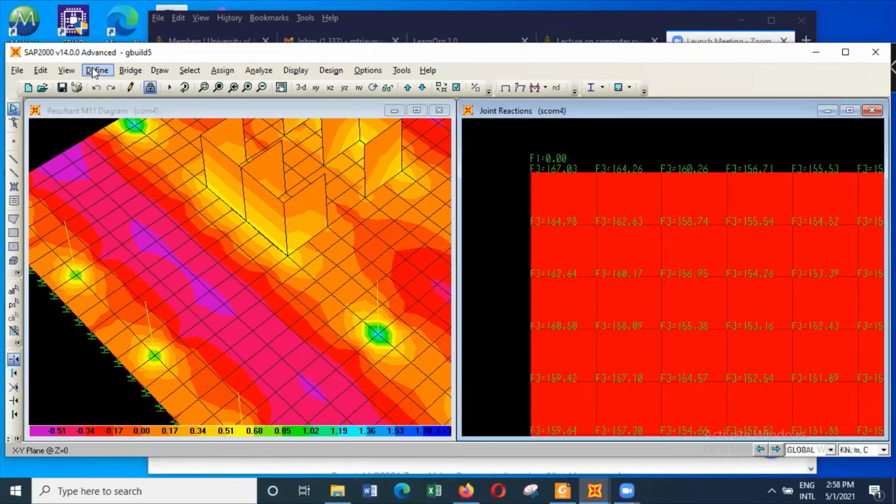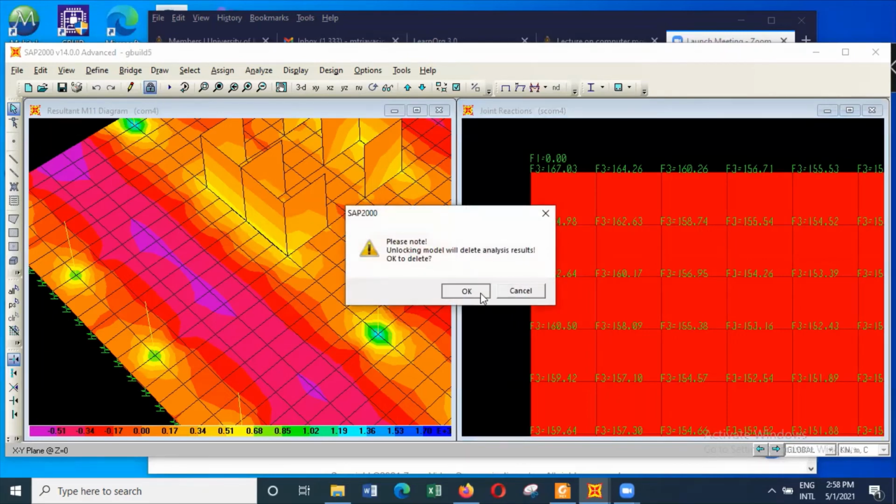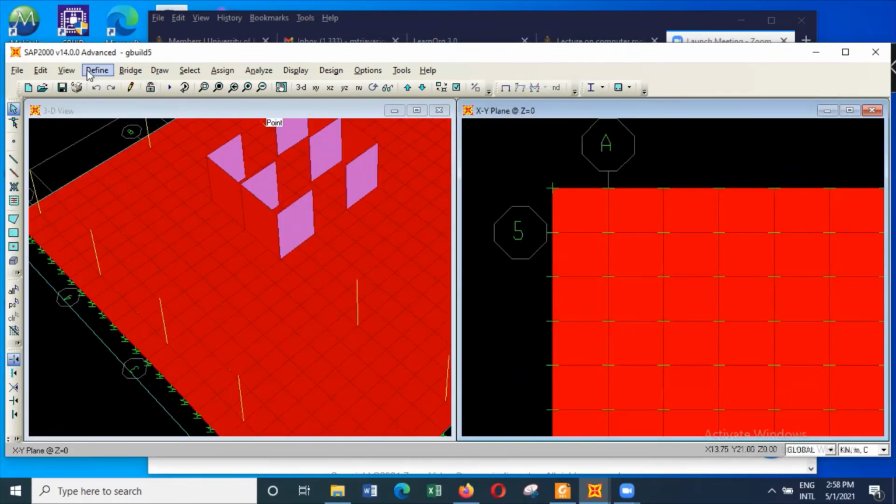So basically what you see is, we have a bearing capacity of about 150, and with the raft, the stress on the sandy soils below would be in the range of 130 to 135 kilonewtons per meter square. So which means, if you wish, you can add another 1 or 2 floors to this particular building. And another thing you can see is what will happen if you increase the thickness of the raft. And here you can see these values: 162, 164, 155, and so on.